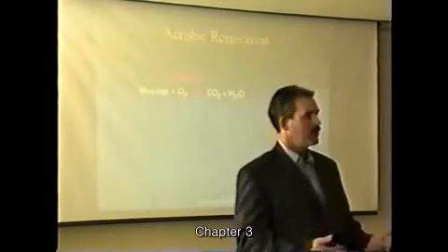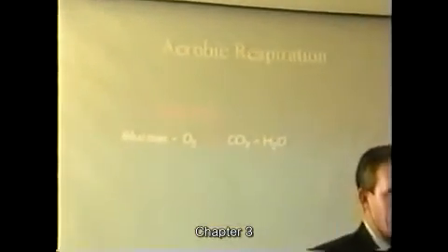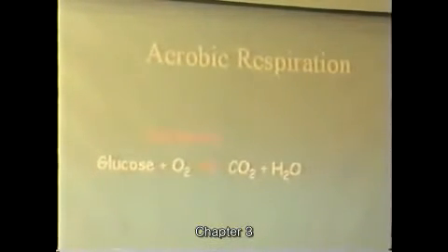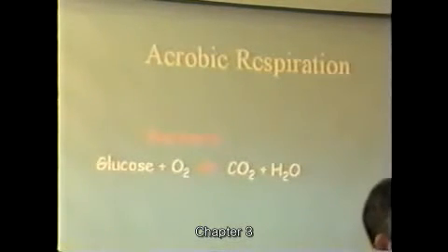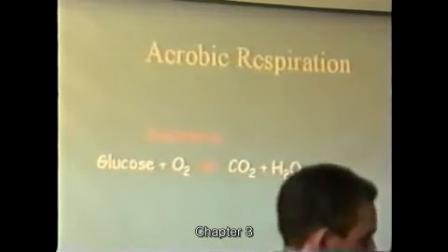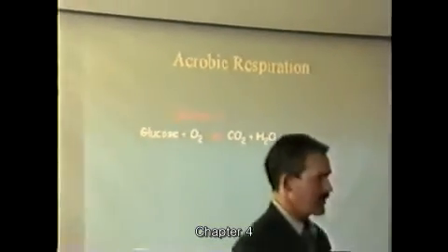If we're looking at aerobic respiration, like we have in an activated sludge system, your bacteria convert glucose to CO2 and water. That's how you're removing your COD. And you require oxygen to do that, and bacteria do that.